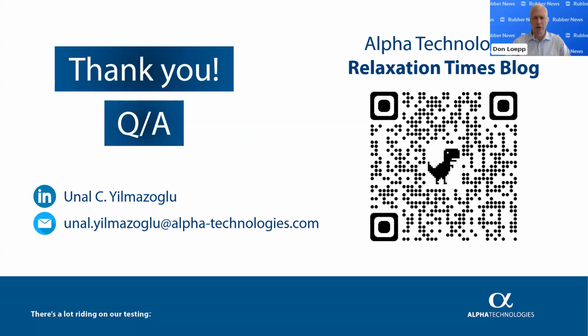Okay, good. Next question. Could you comment on the sub-ambient test capability and how you compensate for thermal contraction and expansion? Excellent question. The sub-ambient temperature testing, which I mentioned from -25 up to 230 degrees C, comes with the RPA Plus. If you remember, the RPA Plus technology, which is the PDM technology, measures the axial sample thickness. It provides a correction in G prime and G double prime values. So you are getting much more accurate values.